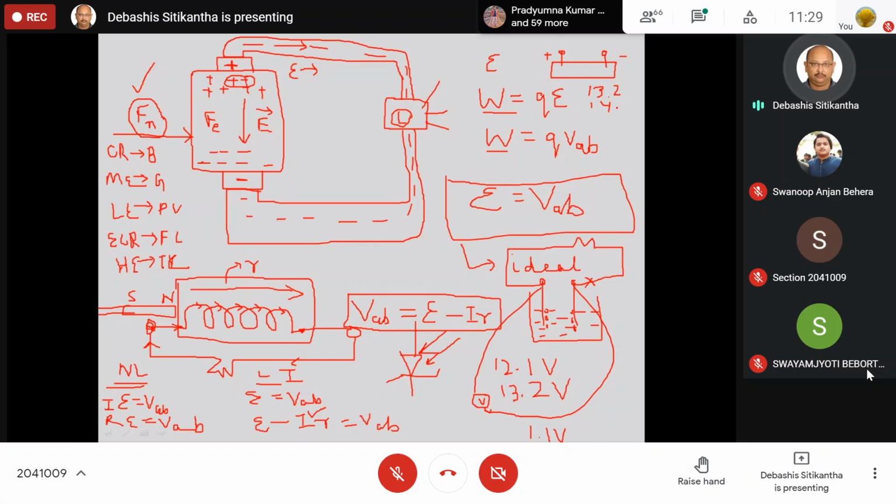So this is under no load condition. When there is no power cut, the inverter battery is not giving supply to the inverter or to the loads. But when there is a power cut, then obviously this battery is responsible for powering your inverter and the loads connected to it. In that case, you will see the voltage would have dropped to something around 12 or 12.1 volt. So there will be a serious drop of around 1 or 2 volt across the battery terminals.